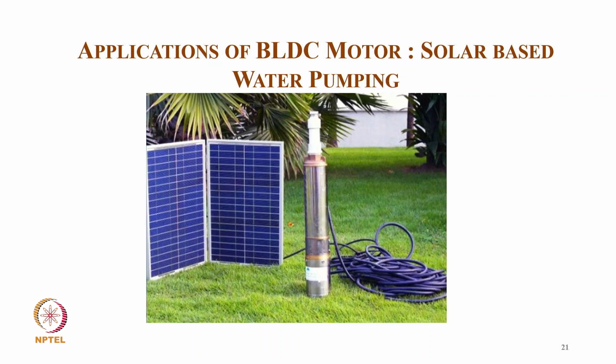So here if we put the BLDC, of course we have to control it with the inverter. So the BLDC gives quite good efficiency. It can give even around 95% efficiency, whereas the induction motor at 1 HP gives typically much less, especially below 1 horsepower.